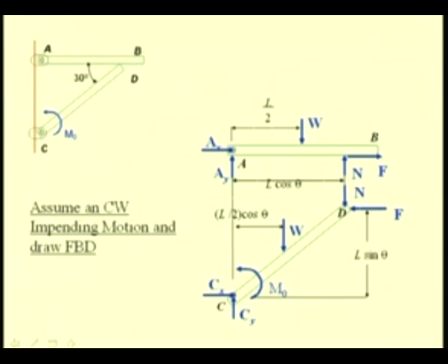So, the force is marked from B to A. On rod AB, this force will be equal and opposite, so it is marked from A to B, and we have the pin reaction at A, the weight of the rod, and the normal reactions as the other forces occurring in the free body diagram. So, from this, let us write the required equations to find the unknowns.